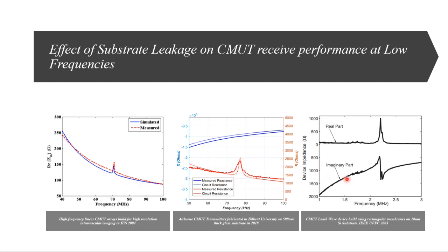And in all these three different cases, which are produced at different times and reported in literature, you see these baselines. Even in the last reference you see over here. Now, what these people claim is that through Doppler vibrometer measurements, they have observed lower order Lamb wave modes in the substrates. So you can see that the baseline is still not flat. Okay, there are some reflections from the structure or the posts of the substrate in the range of about 1.6 megahertz to 1.8 megahertz, and then they have an operating frequency at 2.1 megahertz.